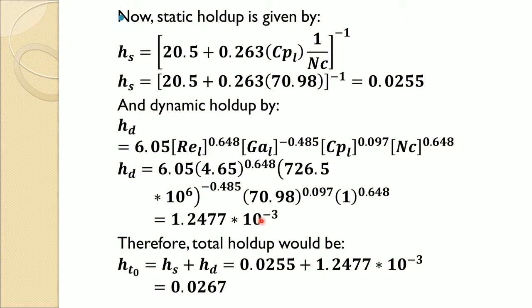If you look at this, the dynamic holdup in these conditions in the blast furnace is usually one order of magnitude lower than your static holdup of the liquid. Static holdup is the liquid held between the particles by capillary force, and it is quite a lot more than the dynamic holdup which is flowing through the void spaces.